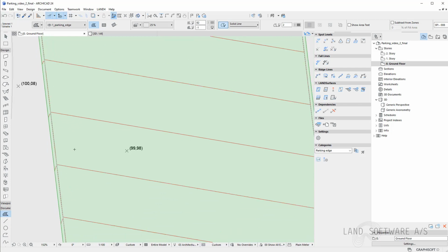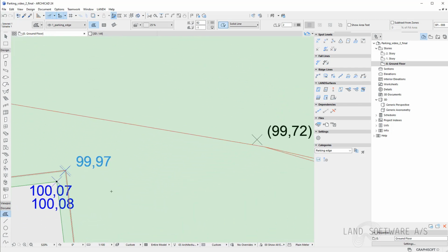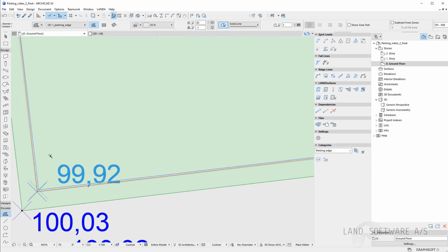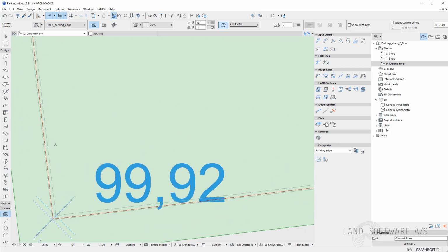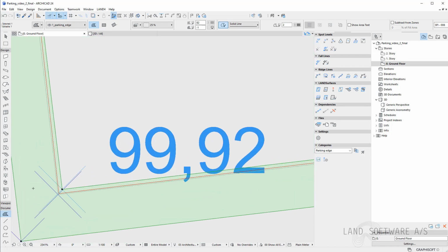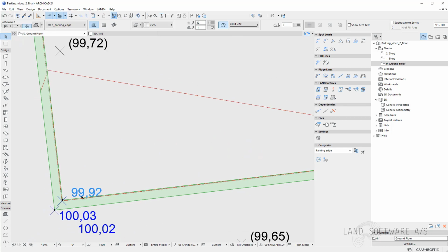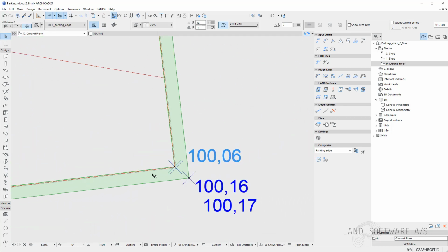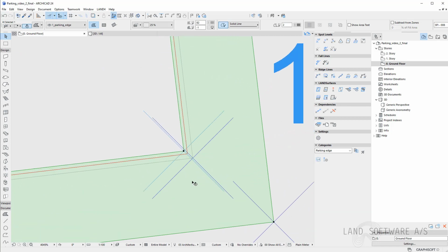And here, using the magic wand, I will basically clip out by holding space. You can see the ridge line representing the surface gets highlighted. So if I click on it now, it will be basically cut at that specific ridge line. Now my new surface is including only the spot levels and the ridge lines I want to have them defined.